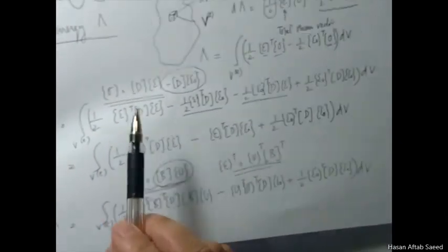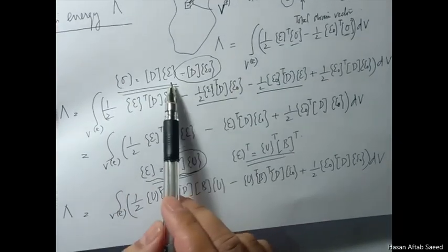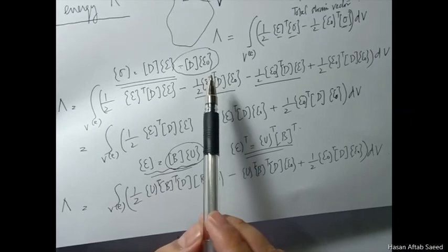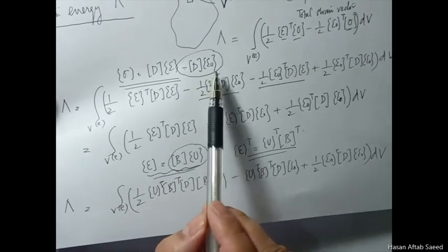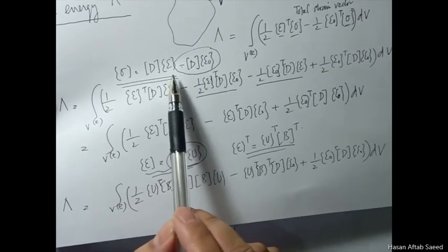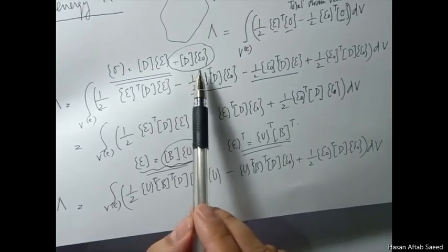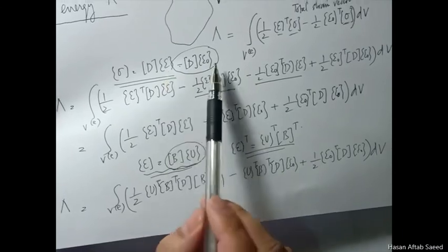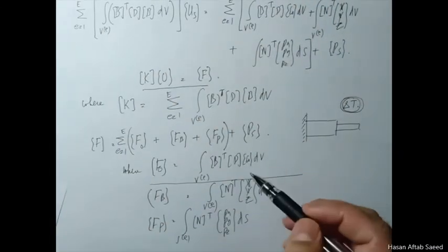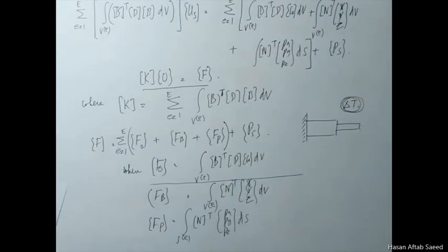So before calculating the stresses, when we subtract the initial strains from the total strains, we'll see that because the whole of the strain is a thermal strain, the mechanical strain is zero, and so the stress will be zero. So this plays a very important part in any problem that has temperature changes in it.